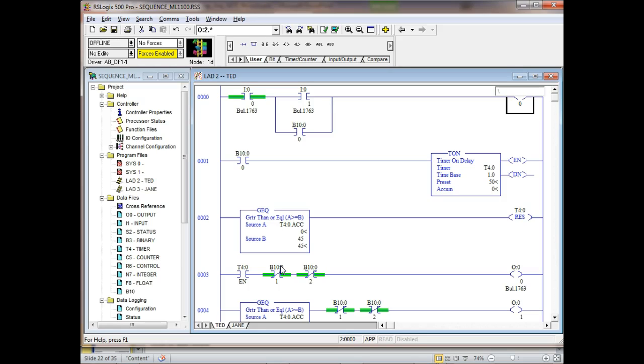Most of your higher level ones, like the 504 and the 1100, you can create just about as many program files as you want to. It tells you how many. I think it's 256. I think they use 8 bits to identify program files. Well, actually not 256, because you lose program files 0 and 1 because of system files.